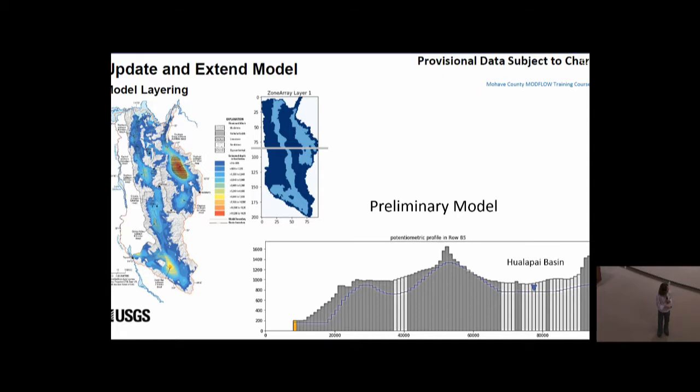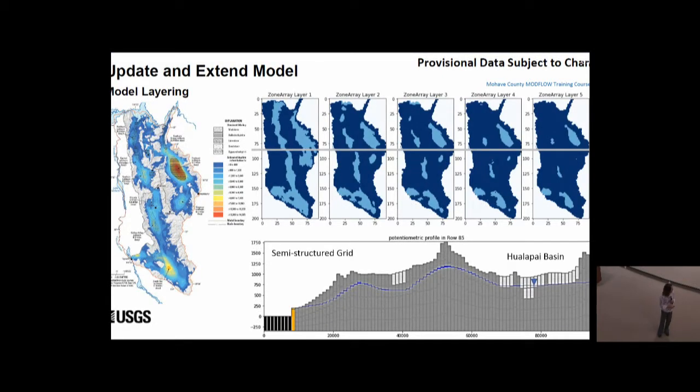Right, let me just show you. That's what Jake did here. Jake at USGS created a 5-layer model in place of the single-layer model, holding most other things the same. But he then cut off the alluvium where most of the wells say it ends. Drillers typically go until they run out of easy drilling and easy water, and then they stop. So if you have a lot of 300-foot wells, that's probably a good indication that that's the bottom of a production zone.